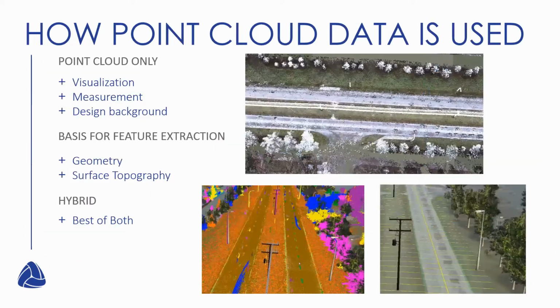So, how is point cloud data used? So firstly, if you're interested in only using the point cloud data, you can use it for things such as visualization, performing measurements, or using it as a design background. Using it as a design background means you would import this point cloud into your design software, and you can then use it as a feature as a whole to perform a design from.